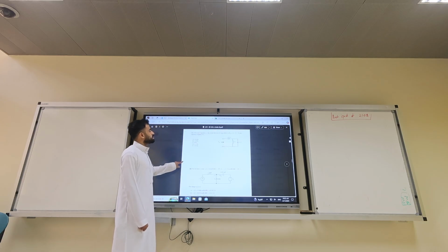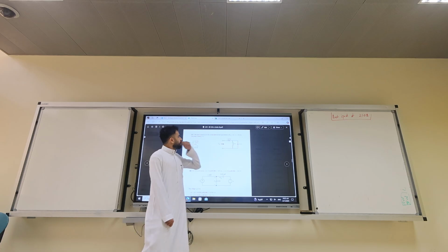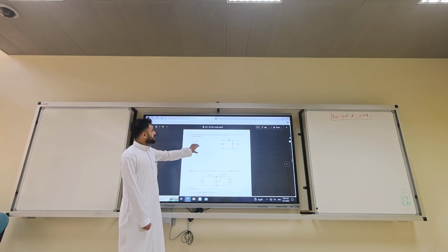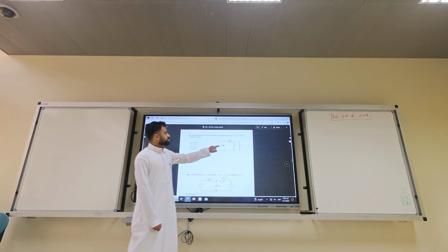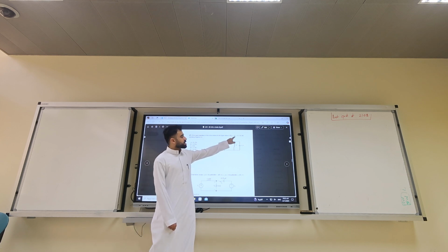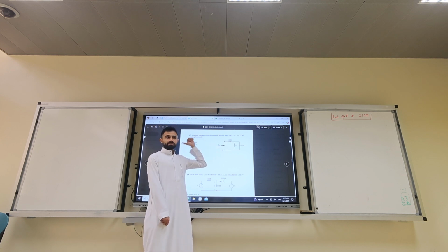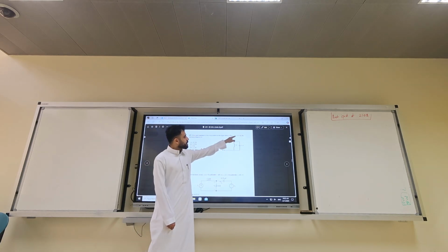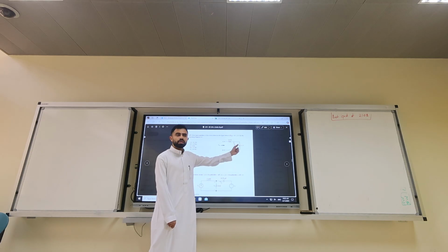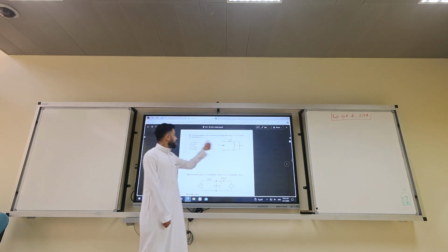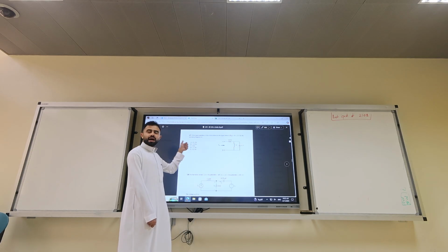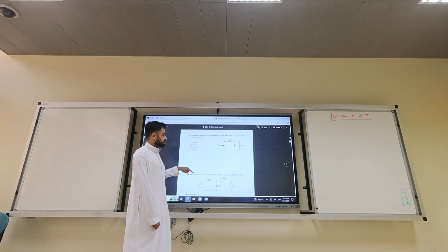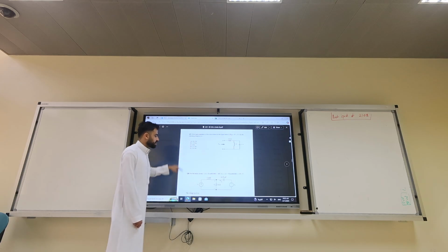What chapter is this, by looking? The input impedance. Chapter 5. Well, this is a tricky question. He's giving you the Z and wants back the omega. So the way to do it is you have to say minus j 1.1 is the parallel combination between those two impedances. And you have to solve for omega, and once you get omega, you should calculate f. This is a bit tricky problem.